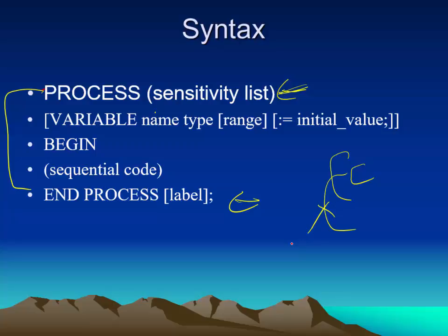Why? Because I just add more flip-flops and more gates wherever I need it. A microprocessor has one accumulator, one set of registers, one data bus, one address bus. It can only do one thing at a time. It goes out, it reads the instruction. Now, I lied to you there. That is a typical standard single-core processor I'm talking about. When we look at some of the multi-core processors, some of those are doing multiple tasks simultaneously. But we're going to assume that those don't exist for sake of discussion.